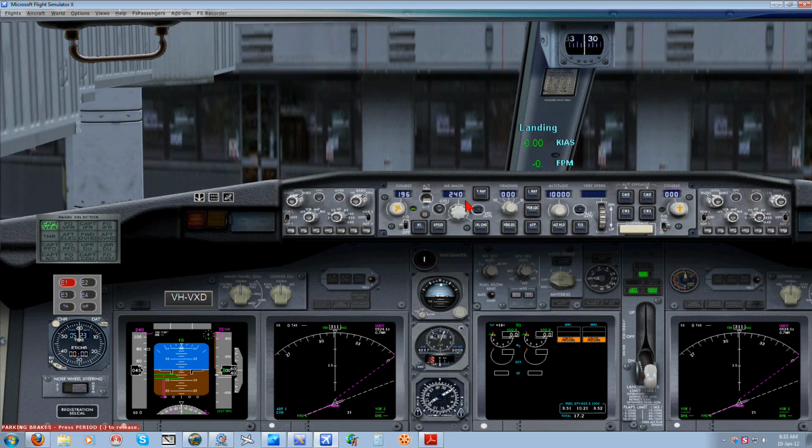Okay, heading again, a heading and course must be the same. So all along we've got the course, the heading, and the first officer's course all have to be the same. So for the heading, we select that for a 6 using the left mouse button, and with the right mouse button we change that till it says 19, and then we've got 196. Okay, so we've got 196, 240, 196.